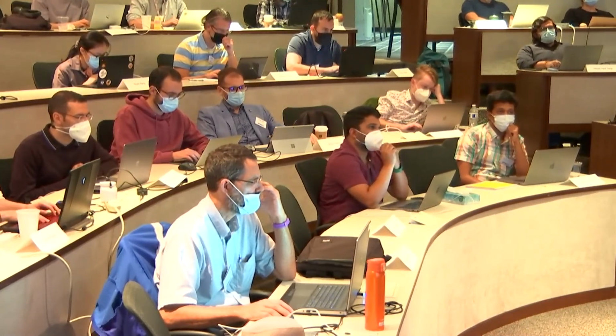So what VisIt is doing is reading whatever data is published to it, and there's all kinds of different data that could be published to it, right? So from uniform grids like what you're talking about, which are evenly spaced, or unstructured grids, which could be arbitrarily complex. VisIt does have a resample operator that will take any grid and turn it into a uniform grid by sampling at different points. So then you could say, well, hey, I have this complicated grid. Maybe I'd like to turn it into something simpler, and I want it to be 1,000 by 1,000 or what have you, right? And then you would have a uniform grid from that. And maybe you could save that to another file format or something like that.